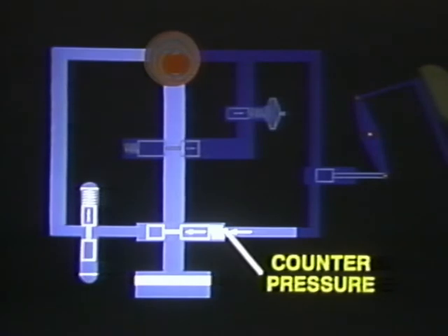Changing the shift points to compensate for the load is accomplished by applying a hydraulic counterpressure against the command shift valve. This counterpressure opposes the pressure created by the governor. This load-dependent pressure is called control pressure.